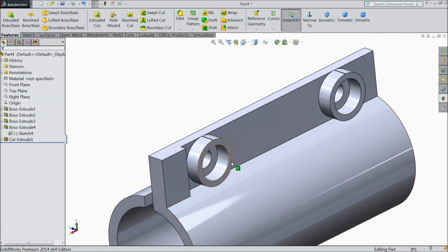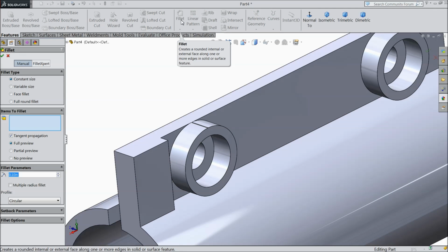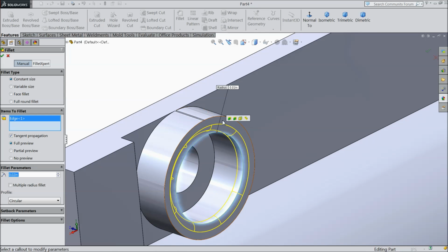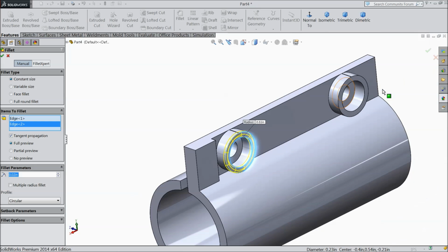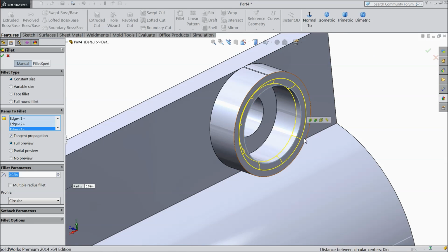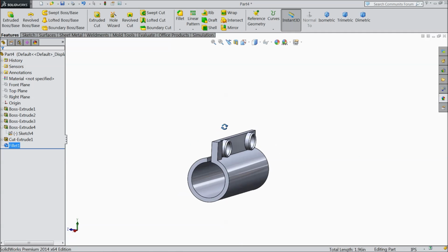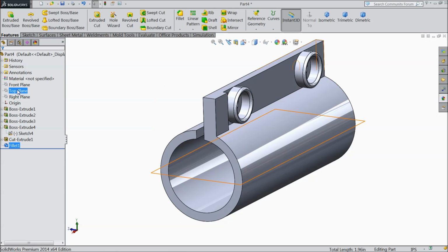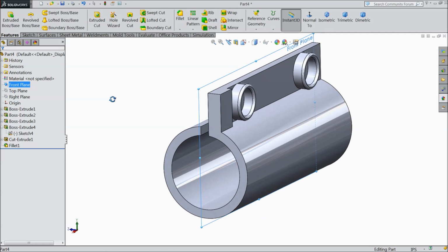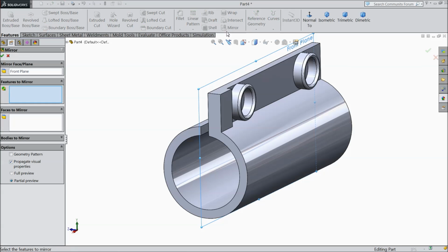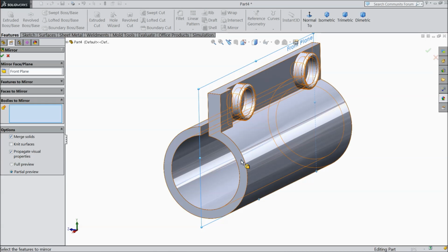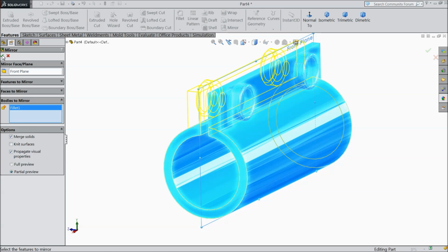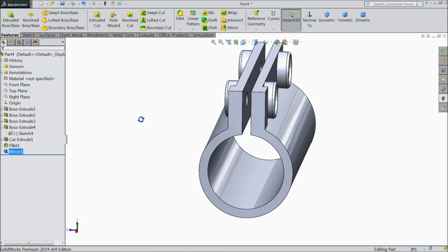Now let's define sketch 0.02. Okay. Now we want to make it mirror. So just do one thing, select front plane and mirror, and select the body and select this full body. Okay. Now see, it is mirror.